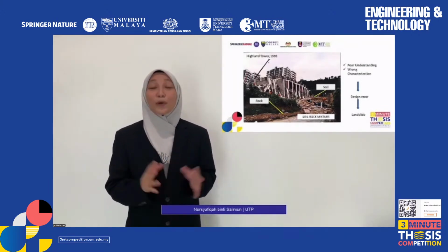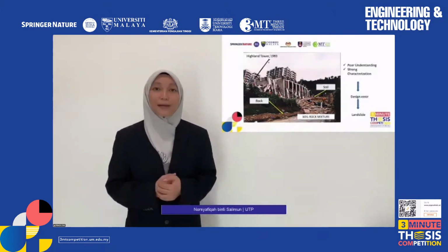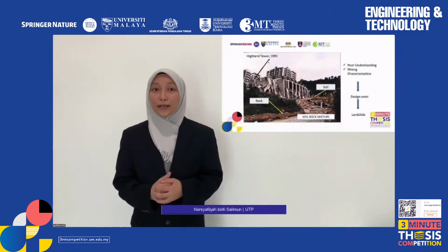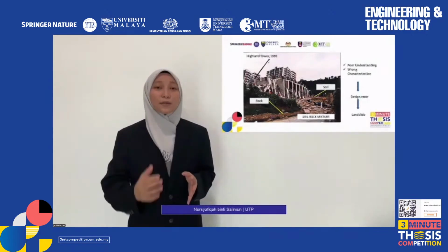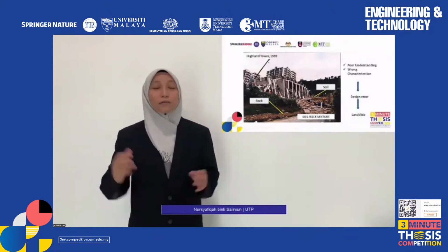By playing around with these parameters, we have further understood how they influence the shear strength of SRM and how to control it. Secondly, we know that the rock block shape has minor influence as compared to the rock block strength. For instance, a weaker angular rock block will have a lower shear strength as compared to a rounded, strong rock block.